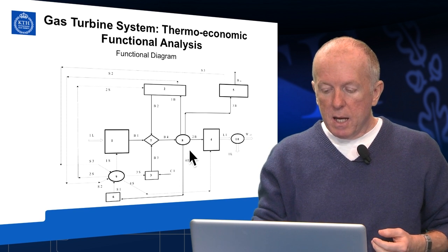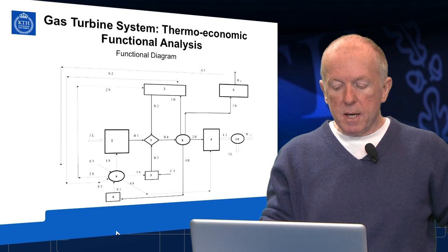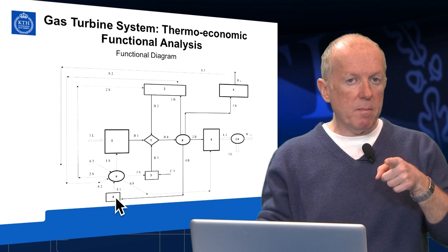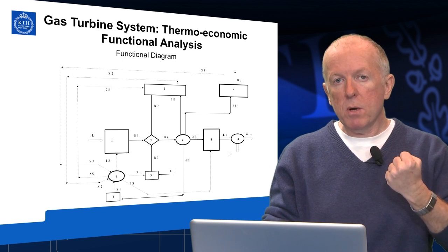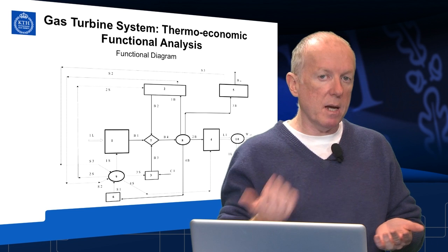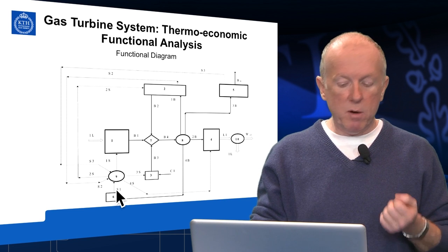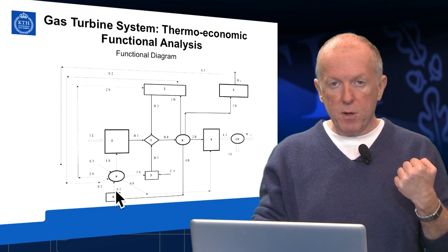So the last remaining part of the exergy, which is the flow exergy of the flow 7 minus the exergy of the flow 0, is the exergy flow 4B. It is given, as you see, to a virtual component 6. This virtual component 6 is the external environment. Okay, this external environment receives the exergy 7 minus the exergy 0, and what is its role? Its role is to close the entropy cycle, like is done by a condenser in a Rankine cycle. This role is the production of net entropy, the flow S1.